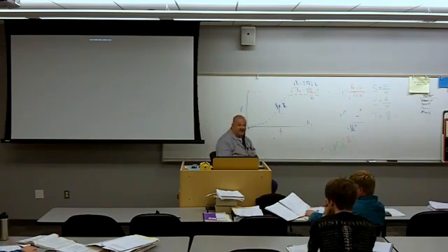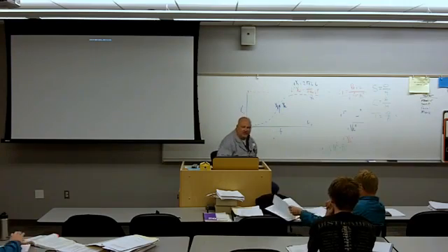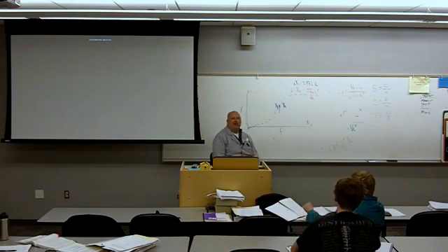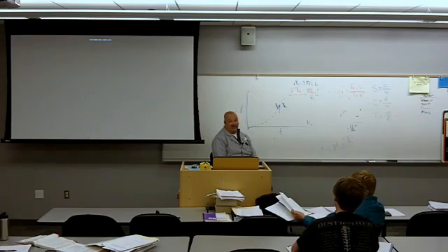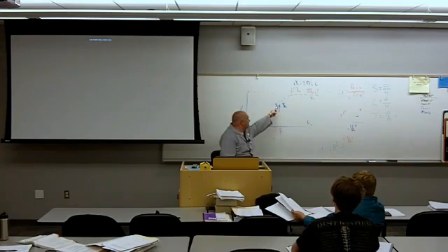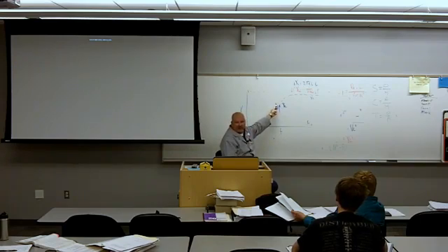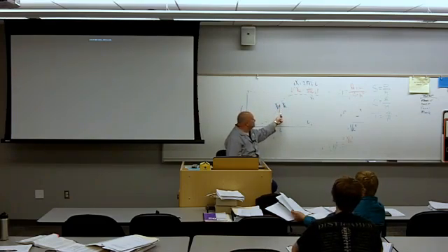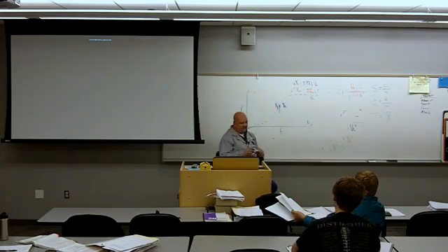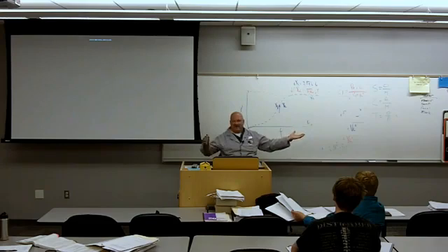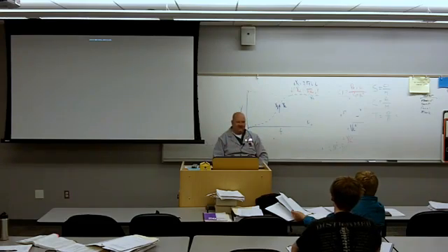Check this out. If I'm below resonant frequency, if I have a series circuit that contains a resistor, an inductor, and a capacitor, and I am below resonant frequency, what kind of a circuit am I dealing with? You're looking at the answer. If I'm below resonant frequency, what kind of a circuit am I dealing with predominantly? Capacitive circuit. If I'm above resonant frequency, what's the predominant value that I'm going to be dealing with? Inductive. The blue cancels out the red, the blue wins, if I'm above resonant frequency. If I'm below resonant frequency, the capacitor wins. So you're either going to be dealing with an X sub C circuit, an X sub L circuit, or a purely R circuit at resonance.